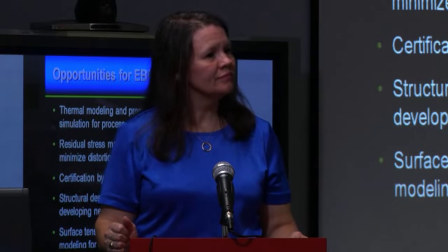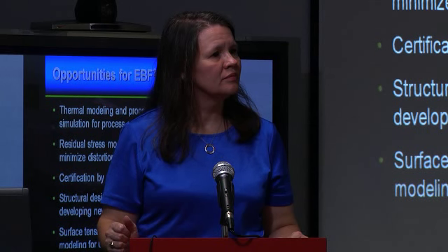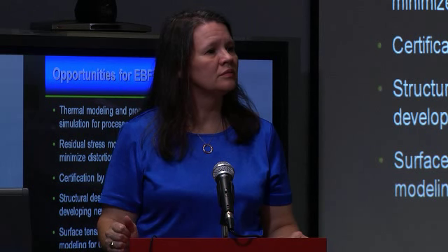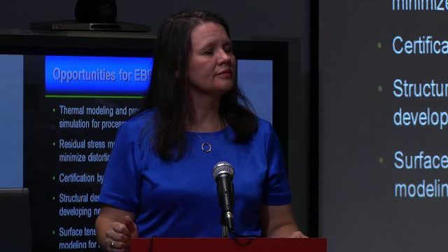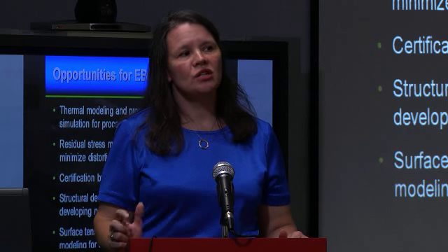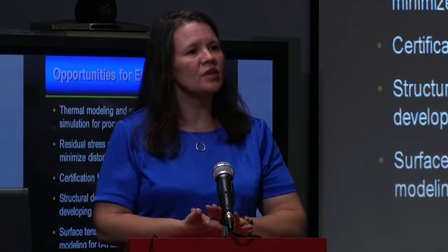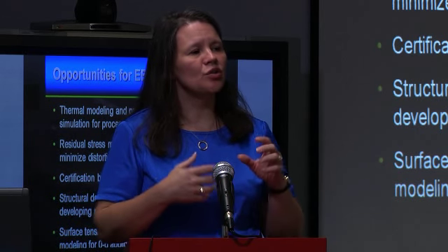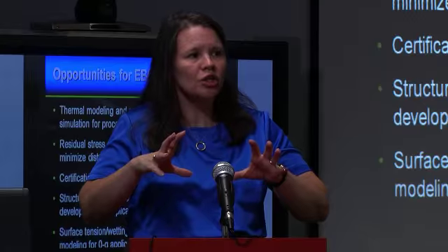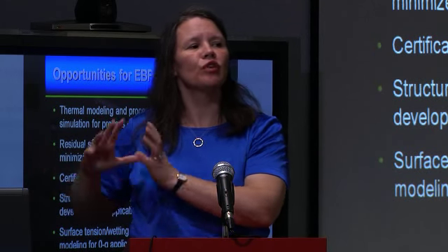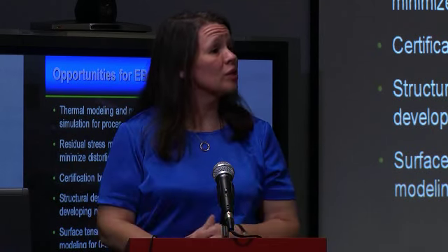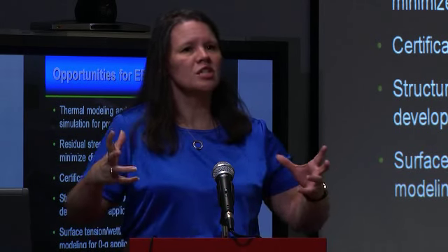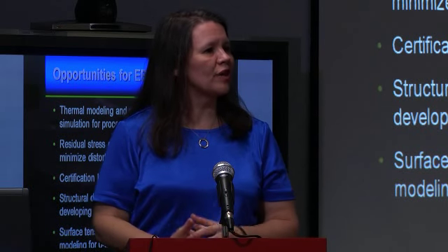I have a question. You were talking about how you get residual stresses near the base. Could the solution be that you heat treat it afterwards to make it go away? So the question is whether one of the solutions to the residual stresses that build up in the base is to heat treat, and that's exactly what they're doing right now. They do an intermediate stress relief: build partially, take it out of the chamber and put it into a furnace to stress relieve it. That's the way we would stress relieve welding stresses, or even machining stresses. There are residual stresses in everything, so that's a very common practice.